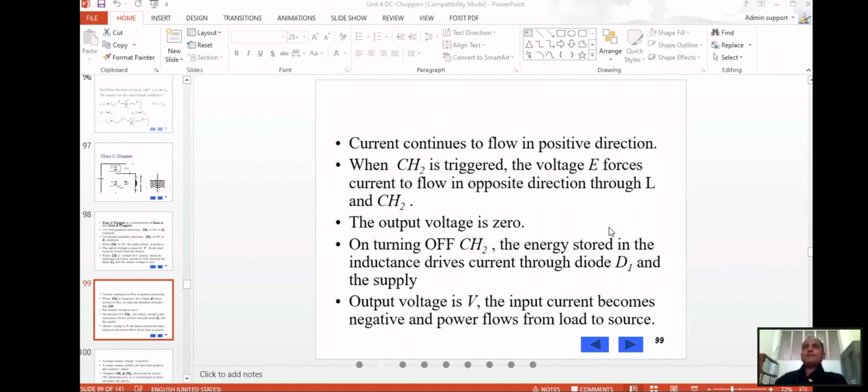Pulse means it's a pulse, right? So in this pulse width modulation, what it's doing is that the time frame T is kept constant. Means the total time period is kept constant, and we are playing with the T on and T off. The other one is frequency modulation. In frequency modulation, it will depend on the total time period, right? So T equals 1 by f.